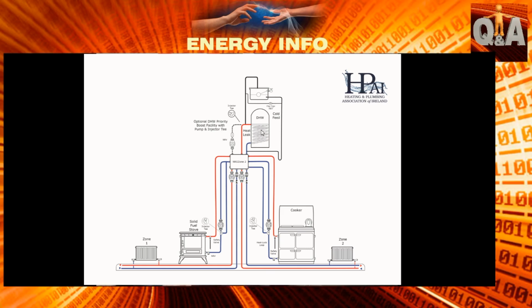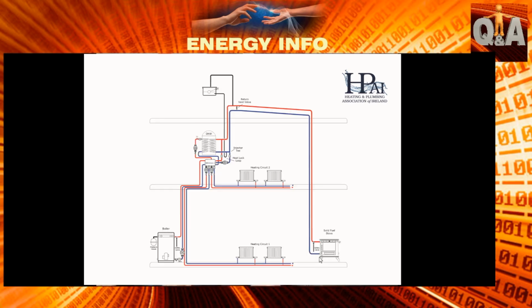Again, here's a situation where you could have, say, a stove on the ground floor and the cylinder upstairs, and again you just rise up and drop down on your flow through the coil and back up around again. But you remember the problem we mentioned a while ago? Well, first of all, you're venting the return on that valve, but also the heat is allowed in that situation to drift back up from the cylinder and heat the pipe in the attic. So it's not necessarily the best way to do it. We can talk about how to fix that secondly.